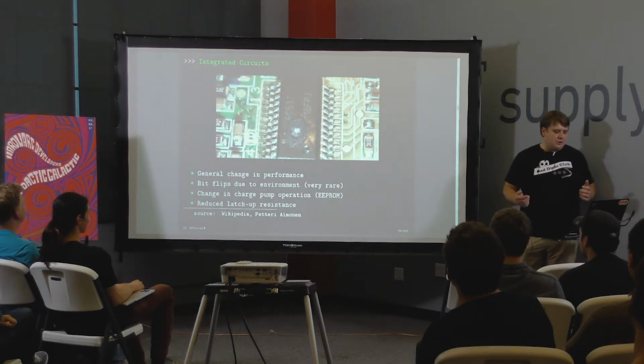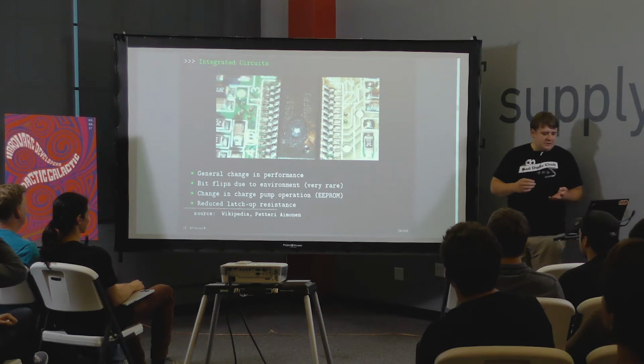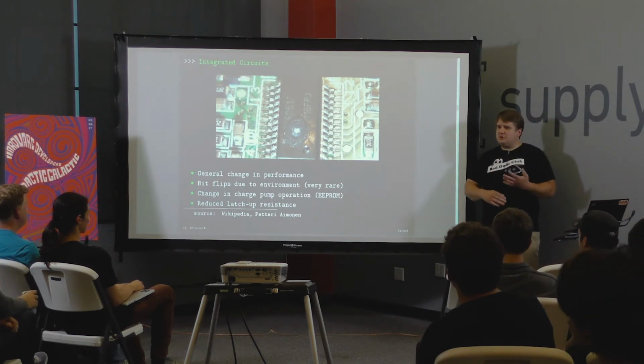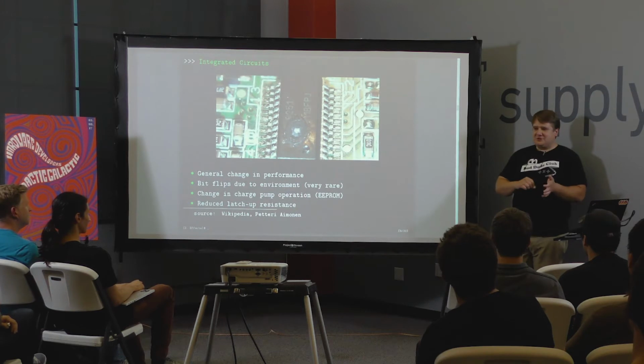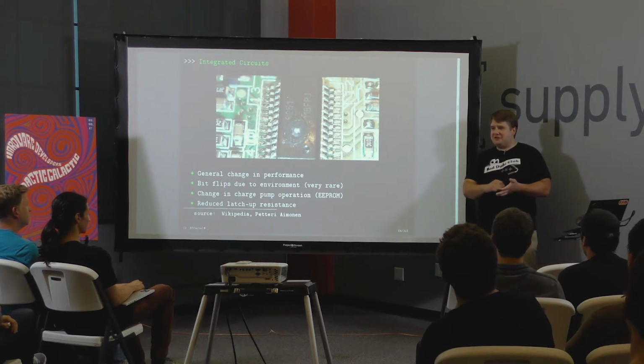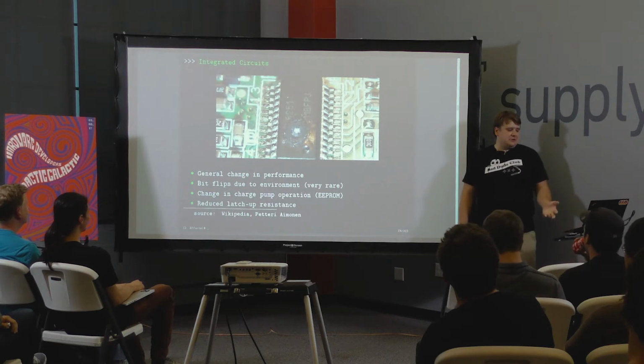So what kind of things can go wrong? If you go to any RadioShack or DigiKey and say, hey, I need something rated to minus 100 degrees C, they'll say, sorry, or they'll just take the minus 40 C rating, cross it out, put minus 100, and hope for the best. So nothing is rated to a lot of the temperature profiles you'll be working with here.